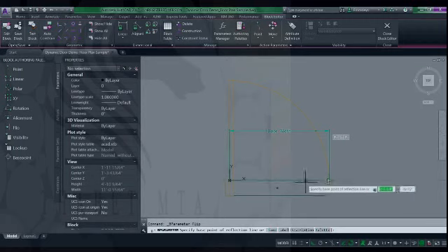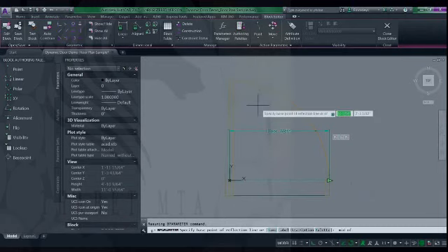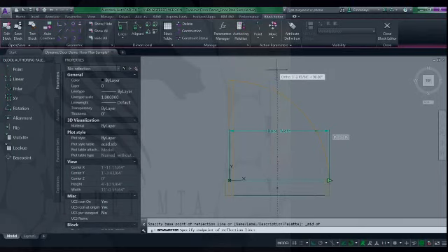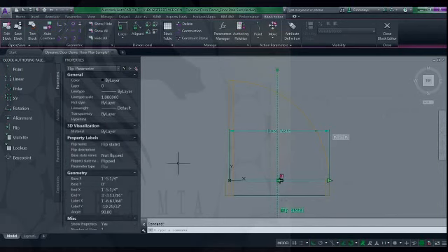And so I need to get a midpoint between my hinge where I put my base point and my door jamb. So if you can't eyeball it, luckily I have this plus mark here that could be my midpoint. But if you want to be sure, you just hold down Shift on your keyboard and then right click on your mouse, select midpoint. So when I hover right there, you'll see that green triangle. That'll give me my midpoint. I'm going to select outside of the door, and then I'm going to put my text down here for my flip parameter. And then I'm going to change that default name so that I don't get confused to flip door right/left.